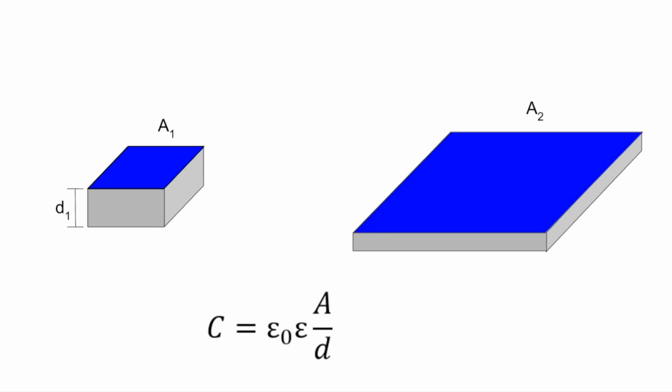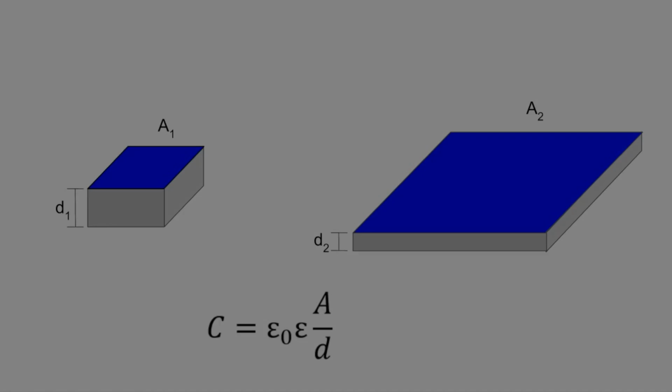On the right side, we have the area in the stretched rubber block, as well as its thickness. From this graphic, you can see that the capacitance will change by a significant amount depending on the stretch. So, not only can DEAs be used as actuators, but they can be used as strain sensors as well. Now that we've gone over some of the basics of DEAs, we're going to show you some examples of what you can make and what materials you will need to do so.